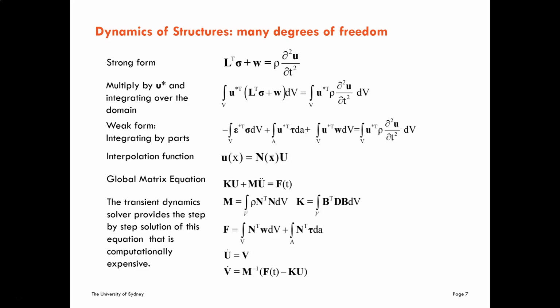Since this transient dynamic solver deals with too many degrees of freedom, all the degrees of freedom of the structure, it's computationally very expensive. And I want to introduce another solver that works with much fewer degrees of freedom. The degrees of freedom in this solver are the fundamental modes of vibration of the structure. So let's introduce the spectral response solver.